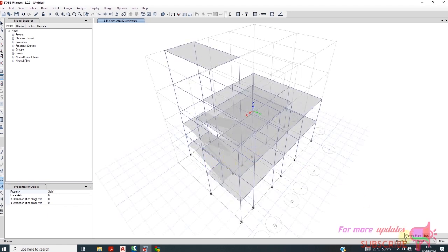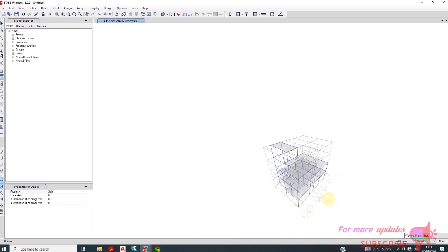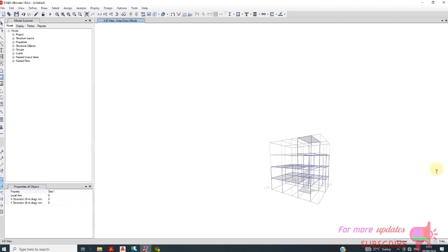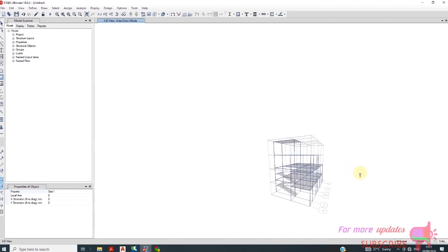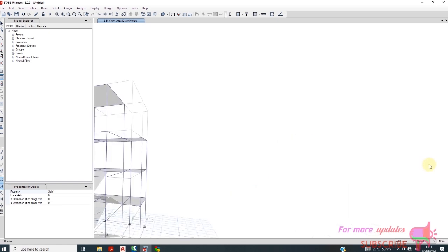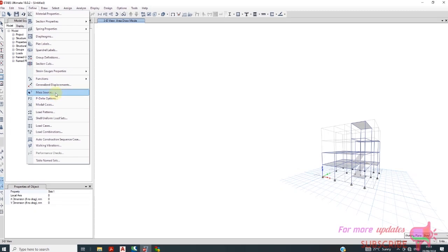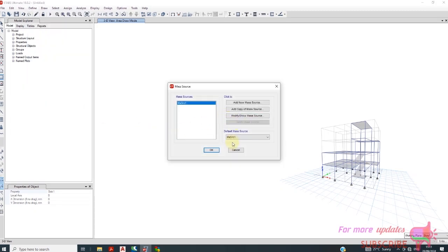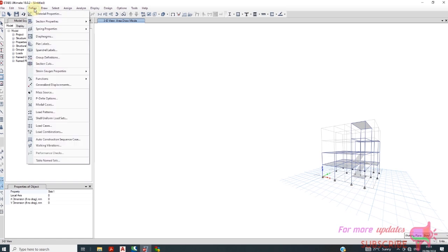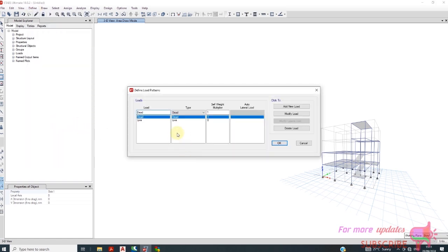Okay. Again, I now change to all stories. So I want to add my loadings to my floors, that is the dead and live load. So I'll go to define mass. Okay, so I'll not modify, define load patterns. I have dead and live load. Okay, so a self weight multiplier of 1 means if I add dead load, it includes its self weight.